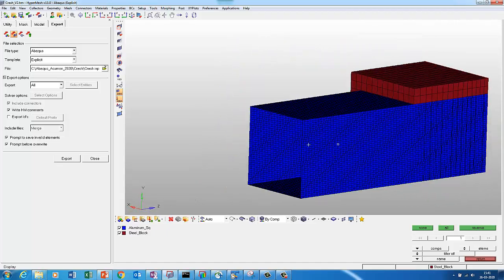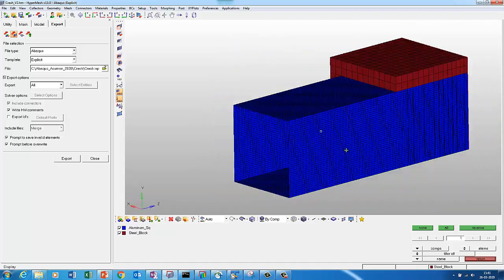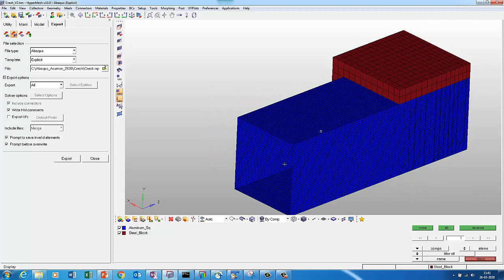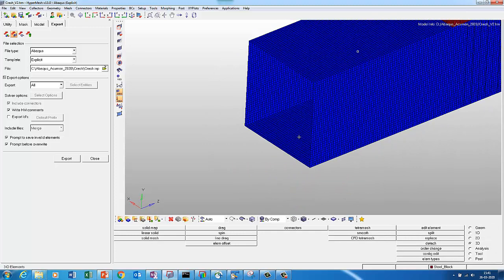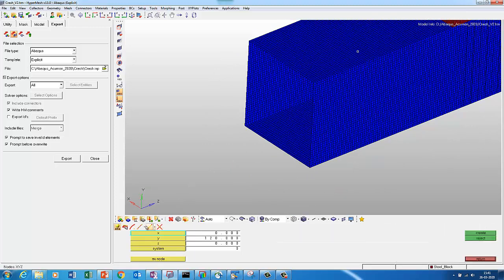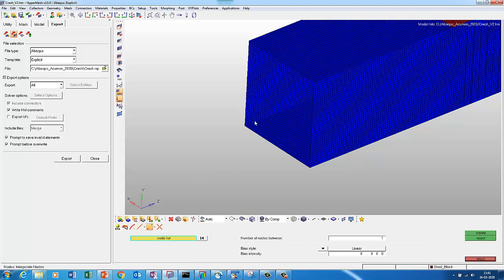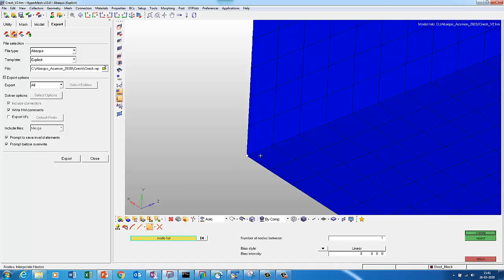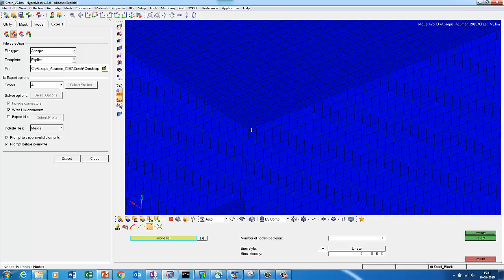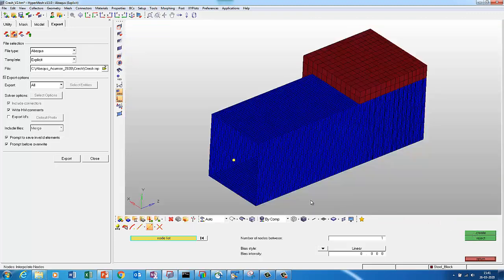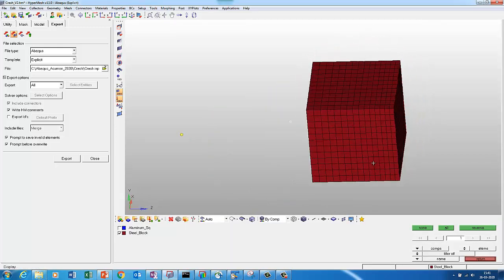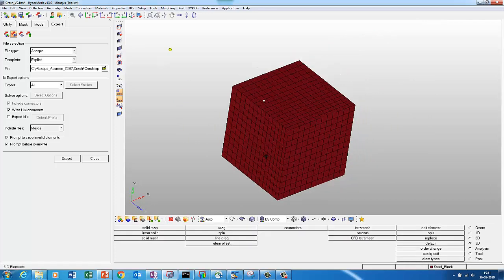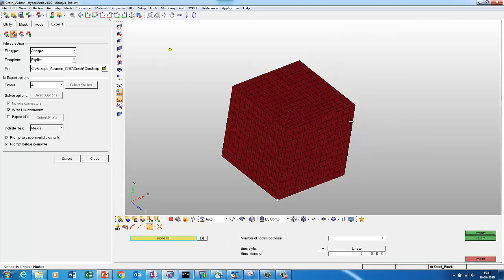So we now got both components we have created. I need to still position it, so one end. So I'm going to position the block somewhere here. So what I'll do, I'll just take a center point of these two. So I say F8 and then I say between, I want this point and this point. I just want a node there. So this is the position where I want to position this, and I take this face and again I put F8. I created this.